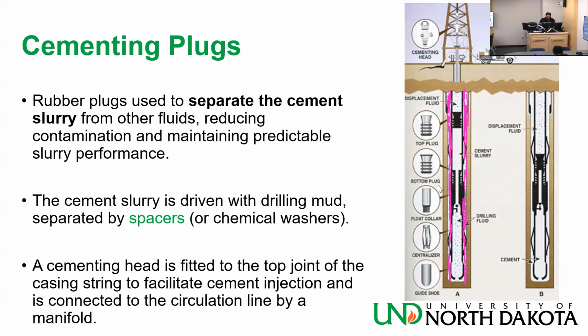The problem is when you don't want the cement to stay here and solidify there, because then you have to go and drill it. Now, if you make the mistake and this whole thing is filled with cement, basically you didn't drill. It's almost like you have to drill a new well. It's almost as strong as rock. So you might as well move and drill another well or sidetrack. This is why you don't want that to happen.